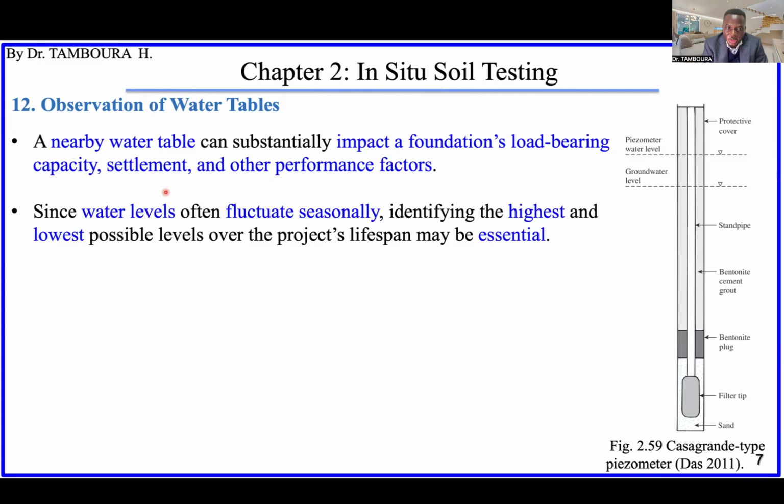Since the water level is sometimes changing, going up and down depending on the season, and some countries have a rainy season and dry season, the water level is not the same. So in that case, it's better to know the highest and the lowest possible water level in the ground for your project.